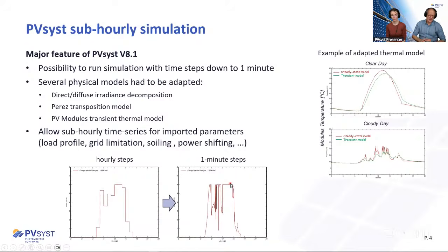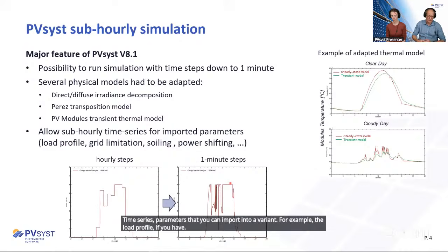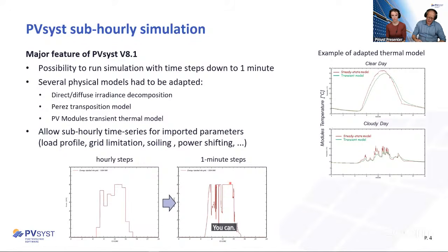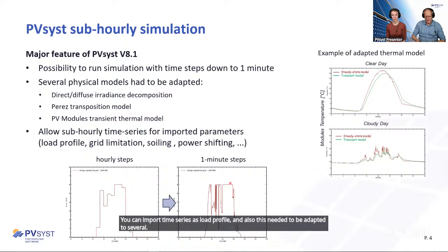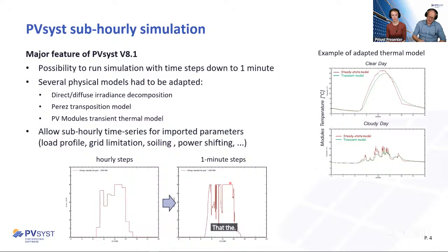The last thing that needed to be adapted before we could really run nicely the sub-hourly simulations was also the time series parameters that you can import into a variant. For example, the load profile, if you have self-consumption or storage in your system, you can import time series as load profile, and also this needed to be adapted to sub-hourly steps to make sure that the time steps that you have in your import match the time steps in the weather file or are matched before we run the